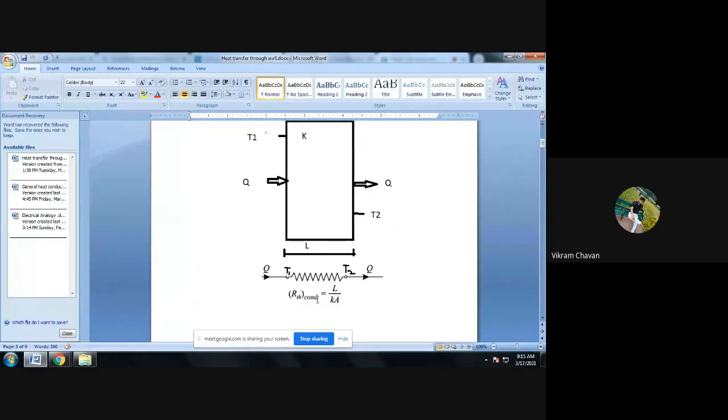If we are measuring the length from this particular point, then at this point x is equal to 0, and the complete length is 10 centimeter at the other end. So x = 0 will be the boundary condition, and the property at this boundary we have to consider. So when x = 0, T = T1 is the first boundary condition.